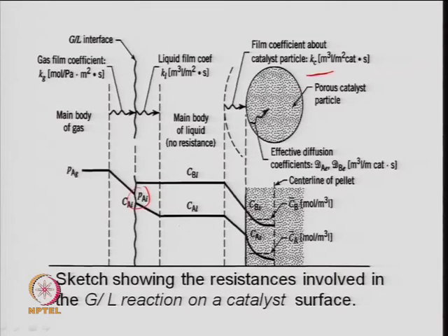So, that is again the transport or mass transfer, followed by the diffusion into the pores, which will depend on the effective diffusion coefficient of A and the effective diffusion coefficient of B, right. Depending upon the type of solid, it may be bulk diffusion or Knudsen diffusion. So, these steps may also control the overall rate of reaction.